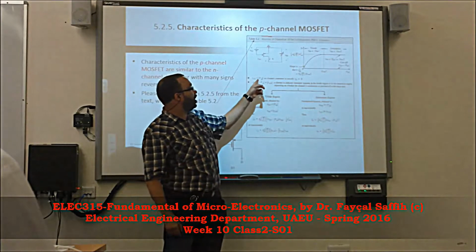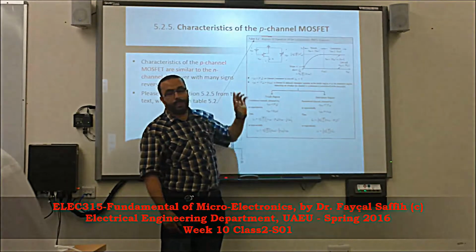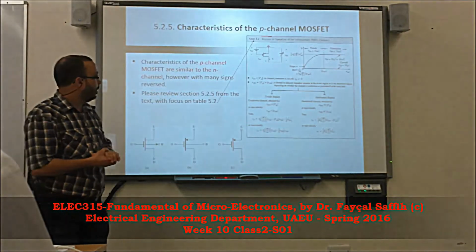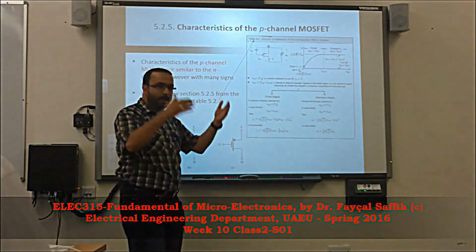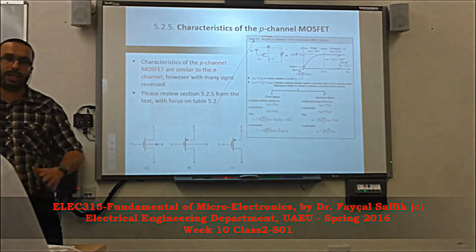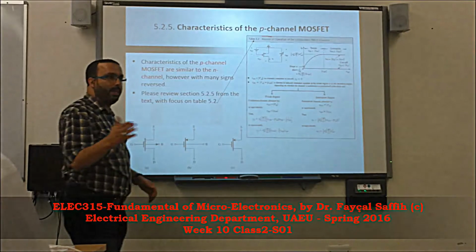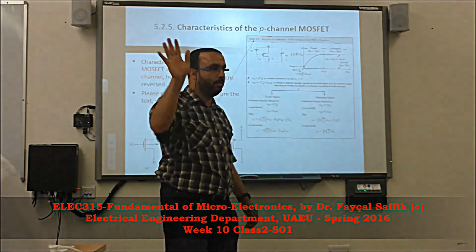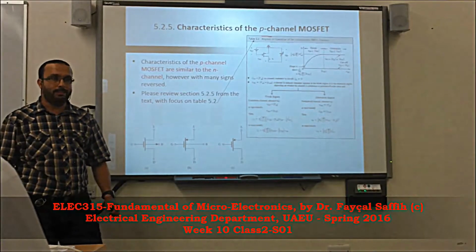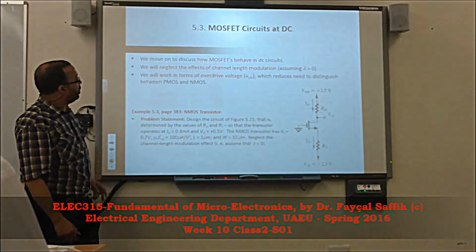Of course, when VSG is less than the absolute value of VTP, we don't have a channel. That's it. Just take the equations and flip everything and replace N by P, and you are in PMOS. It's like a mirror, exactly like a mirror. Alright, good.